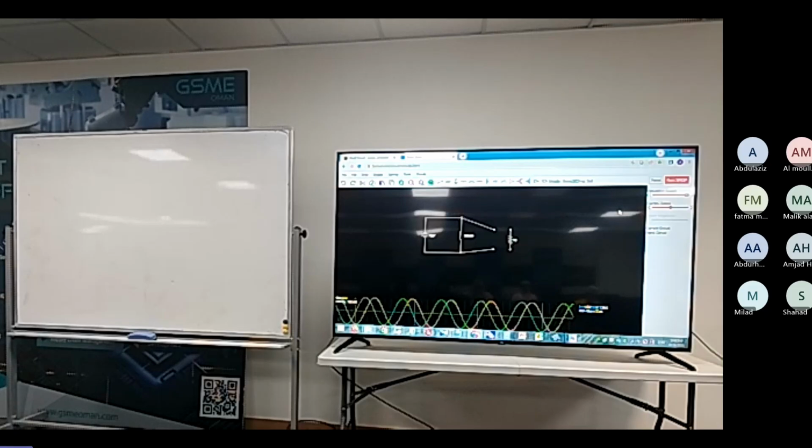It is 1000, right? 150 Hertz times 2 pi, 1K. 1K times 100 millihenry becomes 100. So basically, that's 100 ohm.